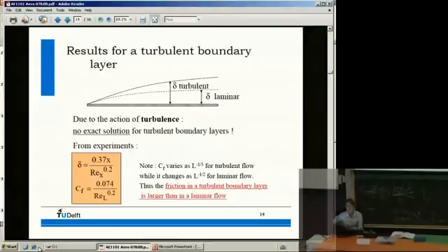Now for turbulent flow, we have similar relations. Why is that relevant? Well, what is turbulent flow? Flow transits at some point, goes from laminar to turbulent flow. How does that happen? Suppose you have very high speed, so a very thin boundary layer. Every wing is a bit dirty, right? You have small spots of dirt on the wing. If your boundary layer is very thin, it hits these dirt things and is perturbed. It is not smooth anymore, but these small eddies start. So then you get transition to turbulent flow. And you get that for high speeds, high Reynolds numbers, much faster than for low.